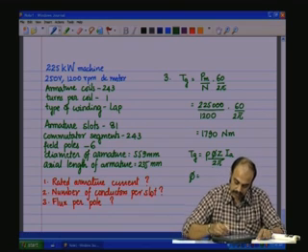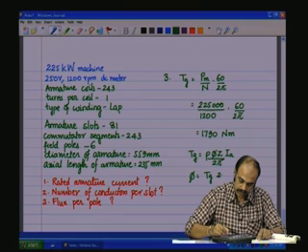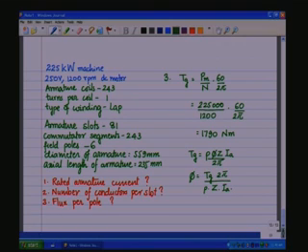So, phi is given by T g into 2 pi divided by P z I a, which is equal to 2 pi into 1790 Newton meter divided by the total number of conductors, which is 486, and I a is 900, and there are 6 field poles.